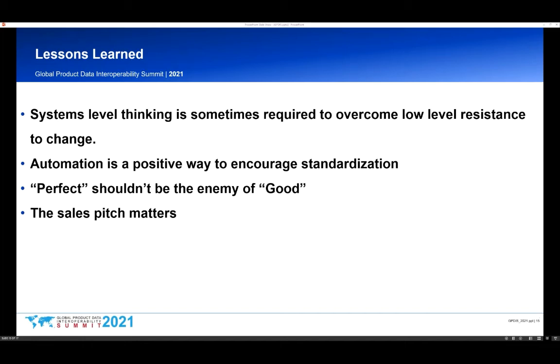We have a process in Boeing for virtually every task that engineering performs. And engineers are also often the very first people to ask the question, why should I follow this process? And if they're not given a satisfactory answer, then they'll sometimes neglect to follow that process. So usually the answer of, we do it this way because then the computer can do it for us, is compelling enough for most engineers to work out how to adjust their processes to do things consistently every time. Small things like using a consistent naming convention, for example, for parts in Enovia, can enable a huge time savings by letting the automation find existing BOM definitions, rather than having to manually dig through hundreds or thousands of installation drawings.